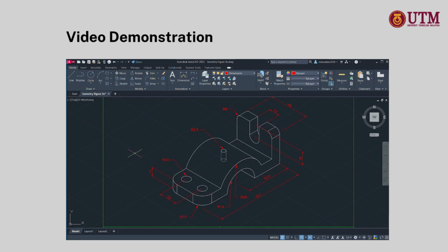Next, we'll be moving to supporting dimensioning elements. Here we can see that these are dimension lines. They are used to indicate the measurement. And then the extension lines are the ones that protrude outwards from the original dimension. For example, this 11 will be the dimension line of 11 units, whereas this red solid line is the extension line, because we should not overlap it with the object.